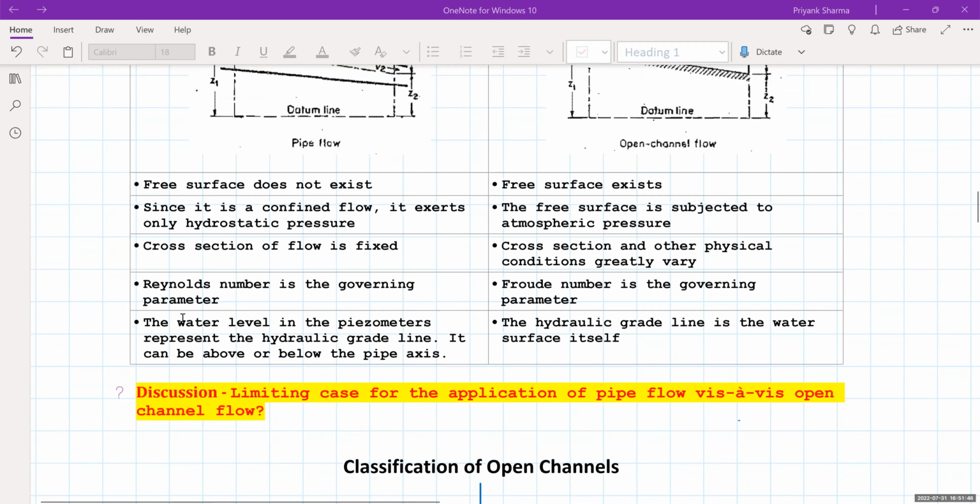Again, we discussed that the water level in the piezometers represents the hydraulic grade line, and in case of an open channel flow, the water surface itself represents the hydraulic grade line. Now there could be a discussion point: what is a limiting case for the application of pipe flow vis-a-vis open channel flow. That is a point upon which you need to ponder, where pipe flow cannot be applicable. However, open channel flow cannot be applicable at many places.